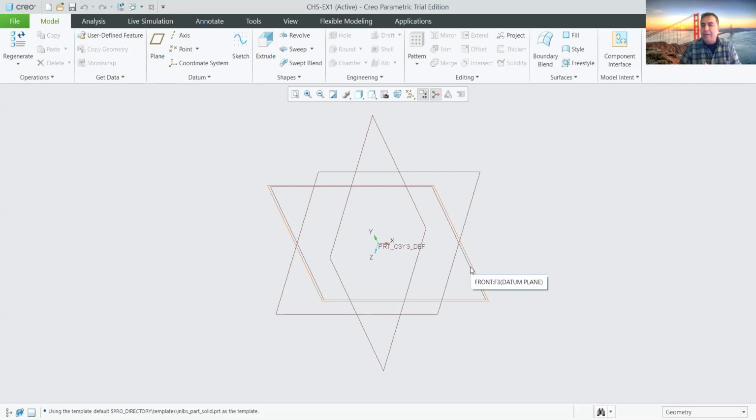Illegal move. The reason is because if you put the drawing in one folder and the solid models in another folder, these 2 folders are 2 independent folders, and the link is missing. So when the link is missing and the solid model must communicate with the mechanical drawing, that causes a big problem. That means I won't be able to open it.